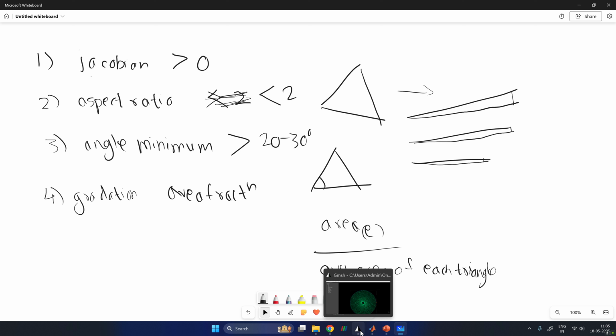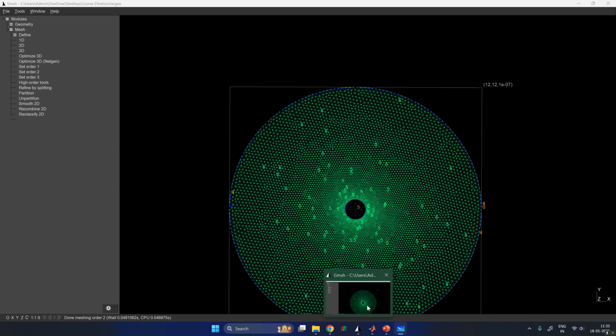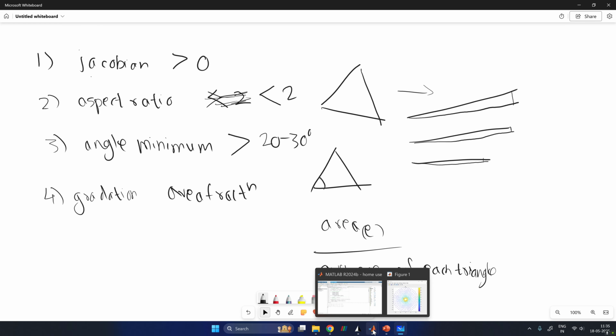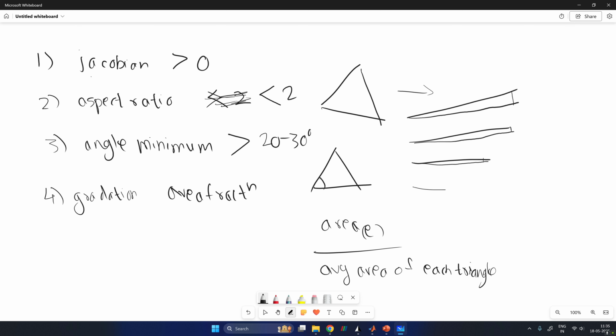So these are the 4 basic points which you can look at, and in case of this problem, which is simple diffusion, it really doesn't matter whether you have a skew in one direction or not. But in case of different physics, you could purposefully increase the aspect ratio in one direction. Okay, and it might allow you to capture the physics. You also have shell elements, for example. So it really depends on the problem. In case of the next course, which we are going to launch for Navier-Stokes, there we will have convection along with diffusion, and then meshing becomes really important.